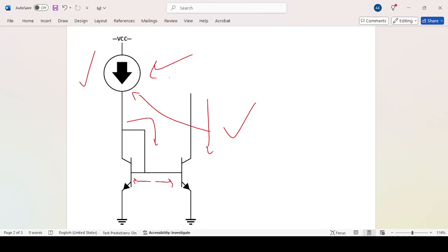So you can have an R out here, which is equal to RO of the transistor, let's say Q2, without adding any RE that reduces your headroom, and which affects things like swing and other stuff, or the common mode range, if you use this current source in, for example, a differential pair.